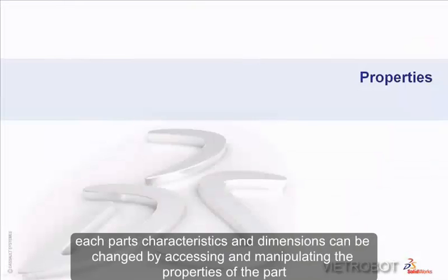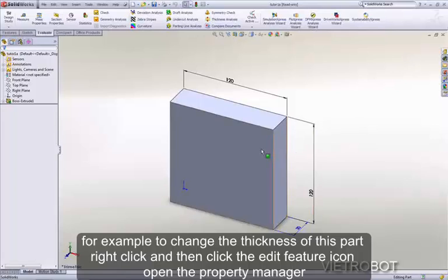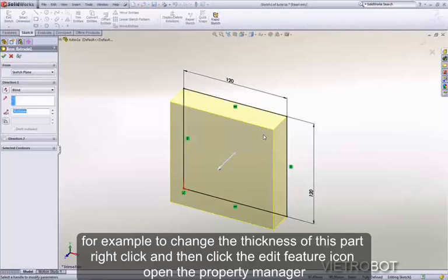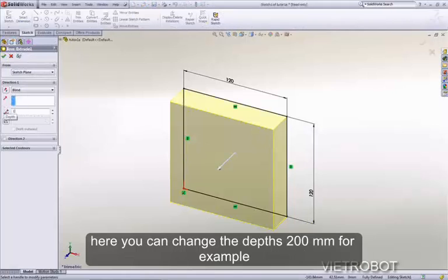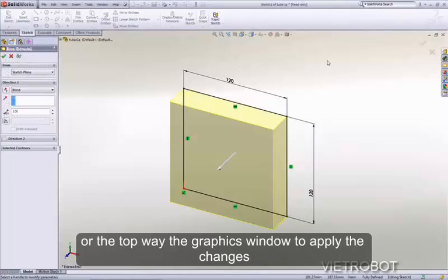Each part's characteristics and dimensions can be changed by accessing and manipulating the properties of that part. For example, to change the thickness of this part, right-click and then click the Edit Feature icon to open the Property Manager. Here you can change the depth to 100 mm, for example. Click the green check mark on the Property Manager or the top right of the Graphics window to apply the changes.